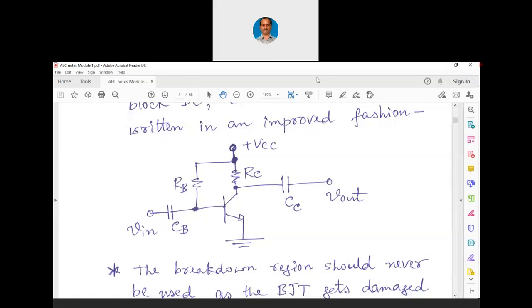So in such a case, if there are such small signals which are going to be sensed, what we are supposed to do is, we will pick up such minute signals and we will connect them not just to one stage of an amplifier, we will have multi-stages of amplifiers. Because one stage of an amplifier may give hardly 60 times, 100 times gain. That is not enough for us because our signal is in 10 power minus 12 or 10 power minus 15.